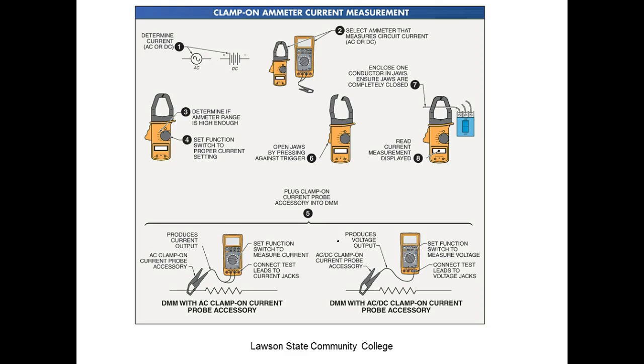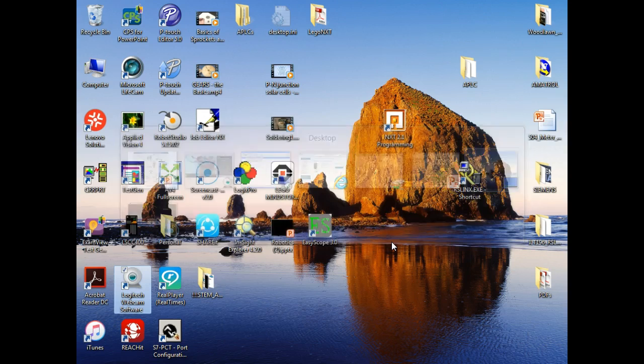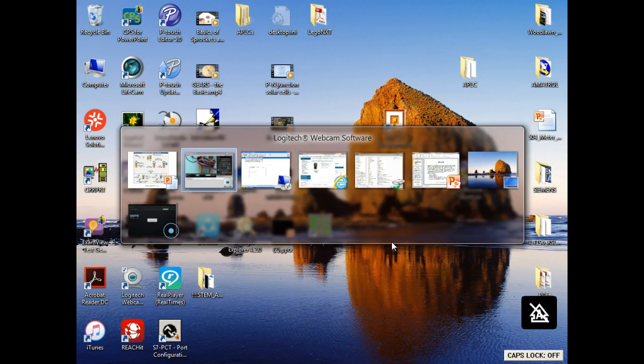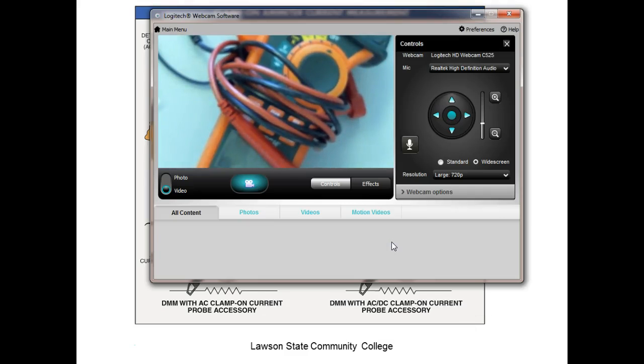By the way, only put one wire through that at a time. If you put multiple wires, the magnetic fields are going to cancel each other out. Y'all understand that? By the way, there is a trick. What determines how much voltage we induce into a conductor? I'm listening. What determines it? Strength of the field. What's the second thing?